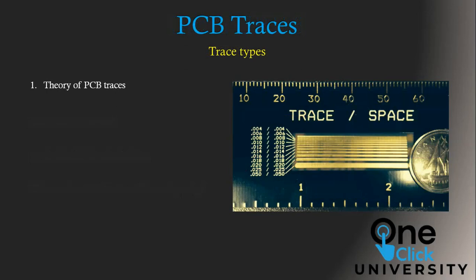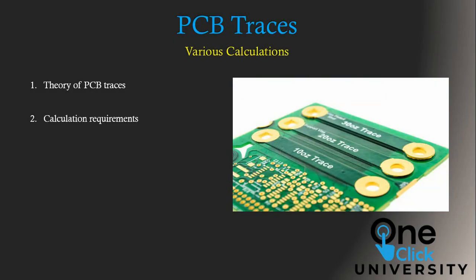The thickness holds an enormous implication for a designer in the design process of the board. If it is ignored, the tracks may not conduct proper signals, which may lead to damage to the board. If the traces are not large enough to carry a certain amount of current, it may result in sparks and also damage the entire machine. So, how wide should the traces be?